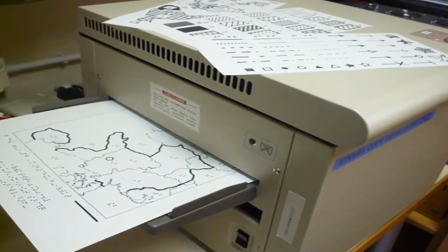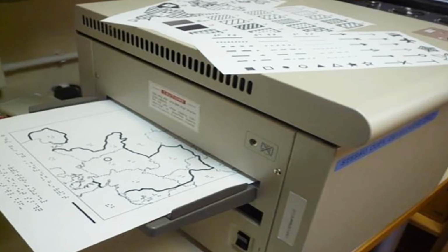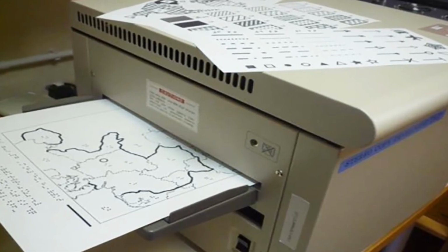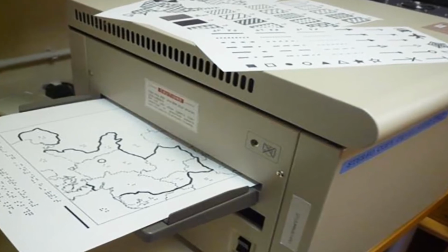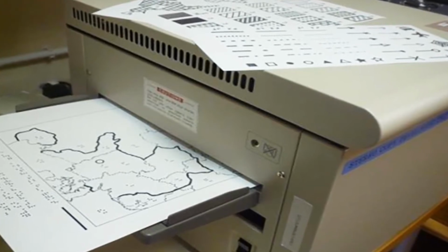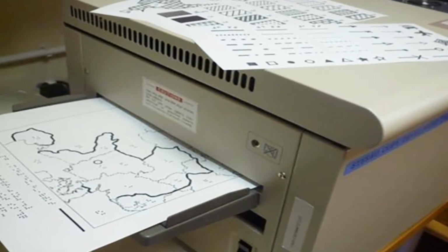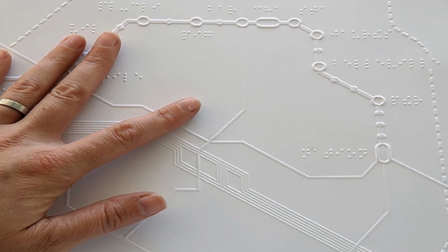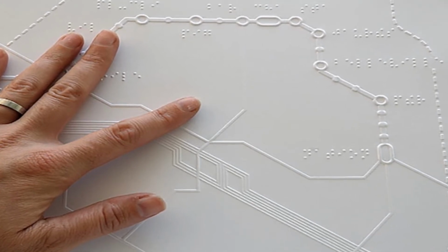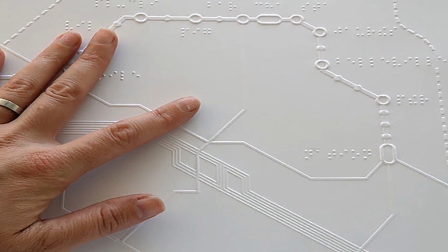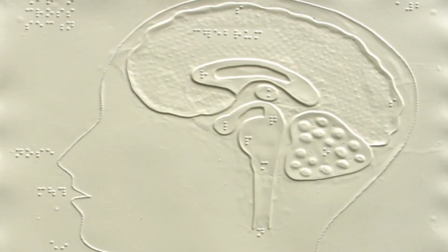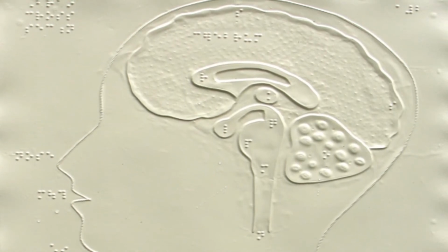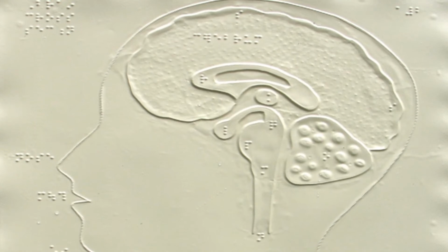The process is scalable for bulk production, but it is very costly and the cost can go up to 200 rupees per diagram. Swell paper diagrams suffer from poor dimensional accuracy as there is a level of directional unpredictability in the expansion of the microcapsules. The paper and raised features are also somewhat fluffy and prone to misinterpretation. There is no control over the height of raised features either. It is difficult to produce a range of true textures as there is a limit to the resolution of raised and unraised areas. Thus, they are more typically represented by patterns.